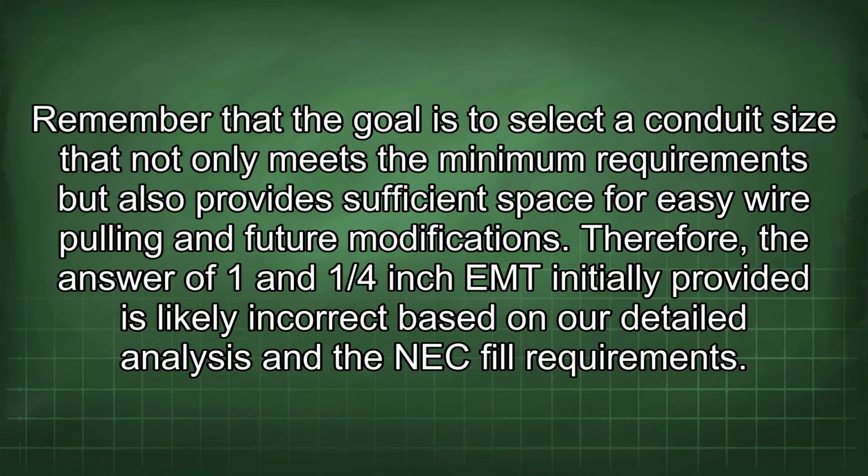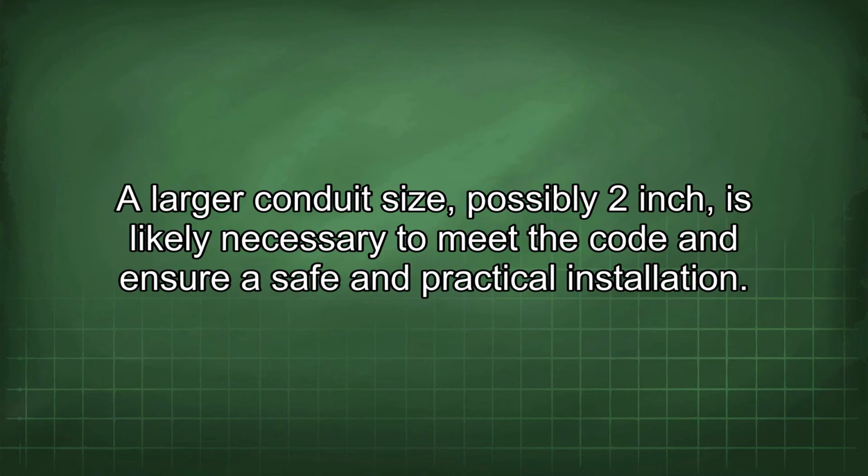Therefore, the answer of 1 and 1/4 inch EMT initially provided is likely incorrect based on our detailed analysis and the NEC fill requirements. A larger conduit size, possibly 2 inch, is likely necessary to meet the code and ensure a safe and practical installation.